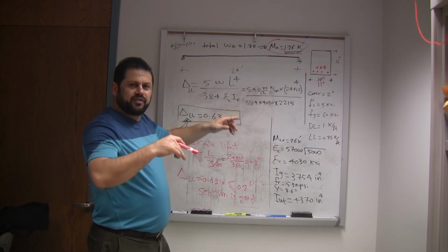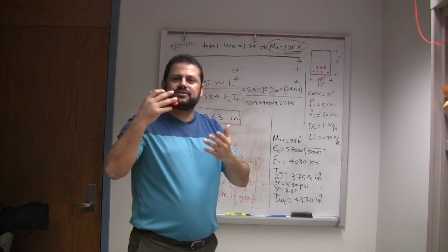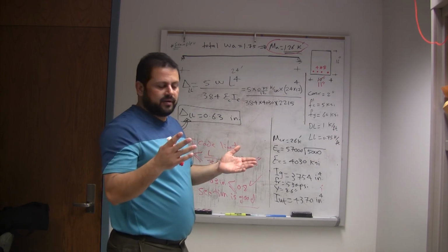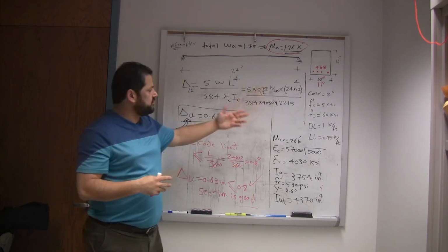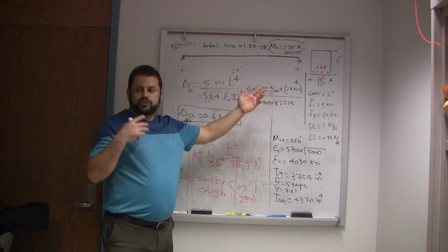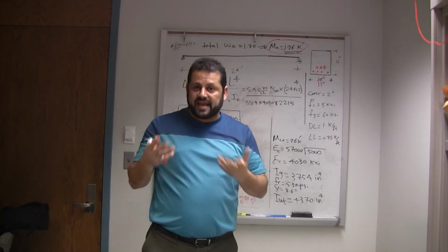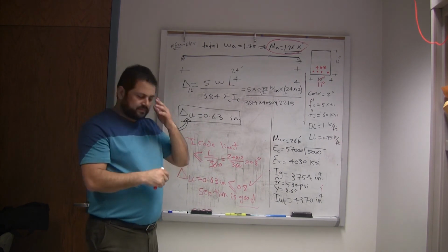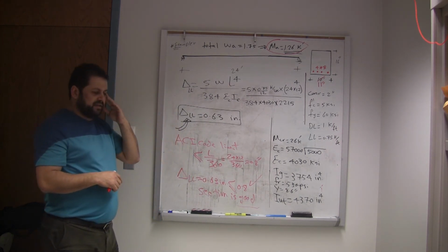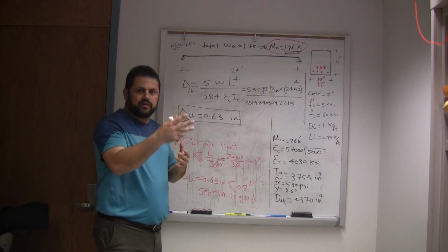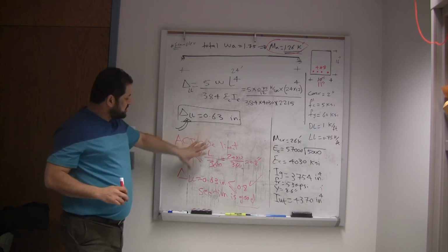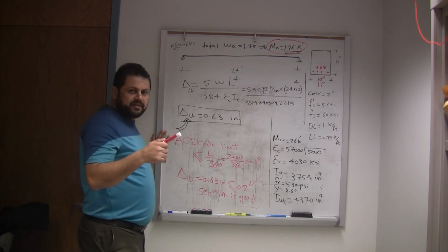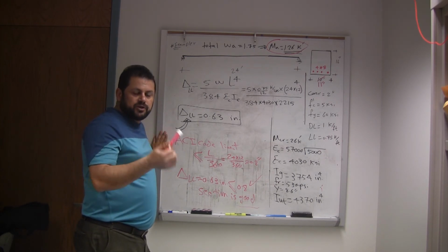And there is another check on the long-term deflection, which usually we don't check. Or we can check it, no problem. It's so easy. You just need to calculate the dead load deflection. You need to know how much of the live load is sustained. Then there is a lambda delta factor based on how many years or months the live load will be sustained. But the most important item that needs to be checked is the live load deflection. And as I keep repeating, the dead load deflection is usually controlled.